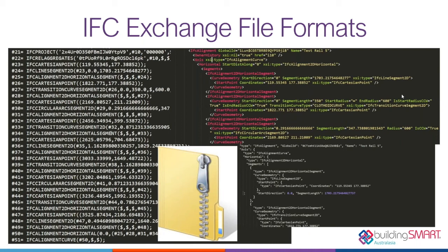Nick's asked a question here: does IFC support civil design elements such as road alignments and profiles? Those sorts of concepts are being added, and there are already some versions of IFC 4 which have been published, IFC 4 X1 or IFC 4 X2. You'll see here, even in this example file that I've picked out in the PowerPoint, you'll see concepts for alignments and positioning systems which have been introduced to that. Again, the sooner we get testing and certification happening on this, the better. The different applications will recognize these concepts.